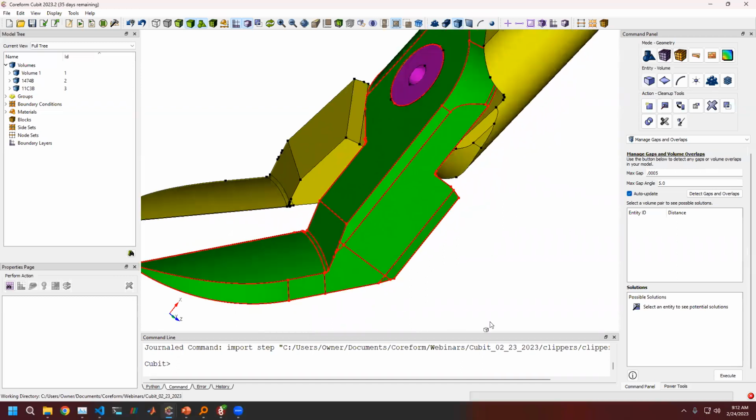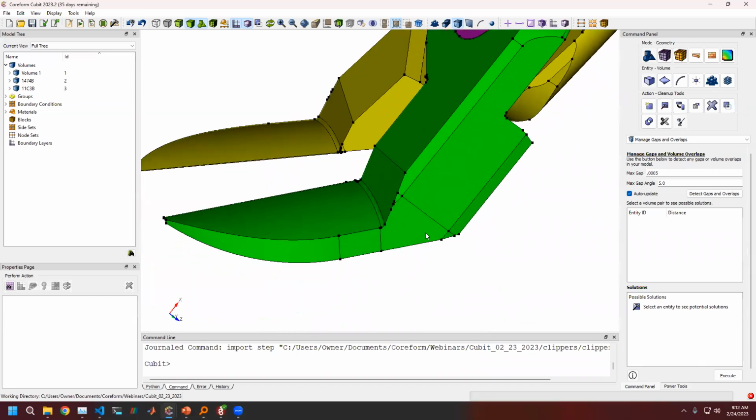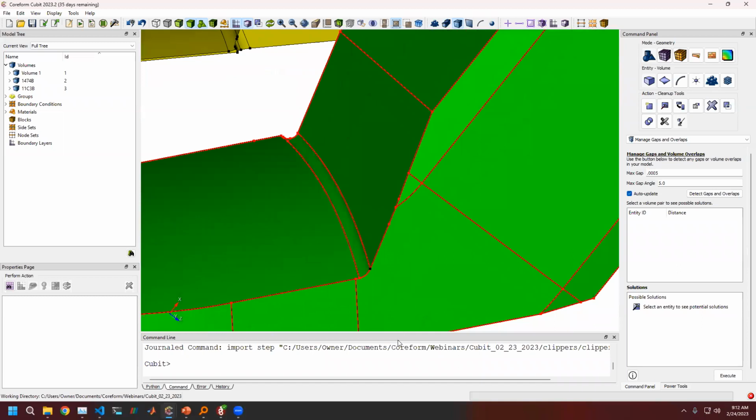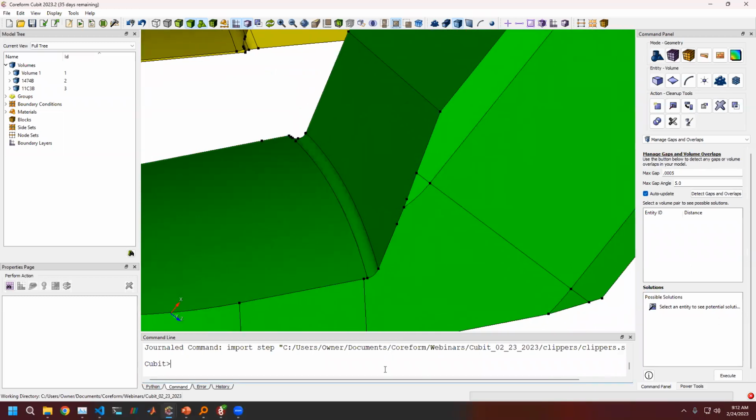Notice one of the things I like to do a lot is I like to see my vertices. This is one good step in trying to help clean up geometry. By default the visibility of vertices is off. There's a command that you can run, it's also available in the tools GUIs. I'll show both processes. If we just type vertex viz on or off, we can cycle those.